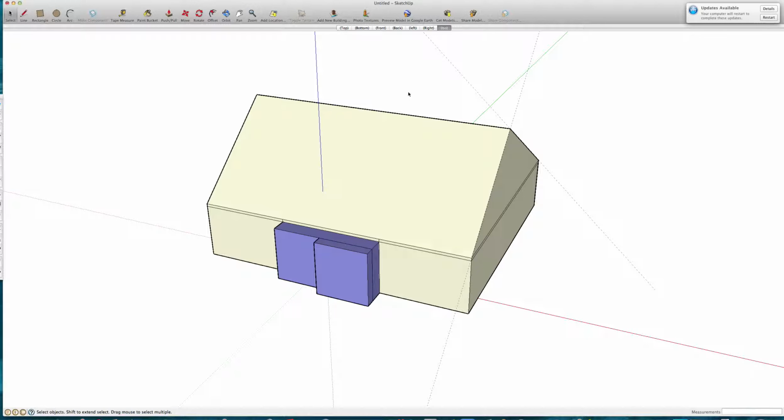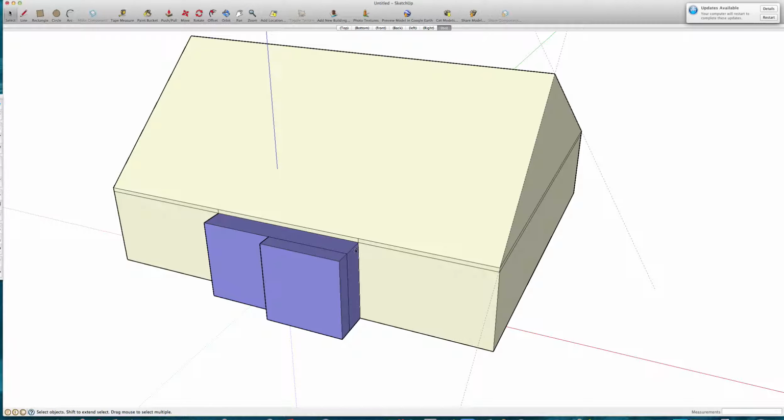Now I'm going to use the plug-in, and the reason I did the 6-inch slice is the plug-in I have is set up to give me a 6-inch fascia at the bottom of the roof slopes. If I hadn't done that, my main roof would be too low by 6 inches. So I'm going to create this first gable, followed by the second. Now behind the scenes, I'm selecting everything and exploding it. If you don't explode a roof created with a plug-in, when you go to erase this line, you're going to erase the whole thing. So I exploded it first, then I'm going to erase this line.